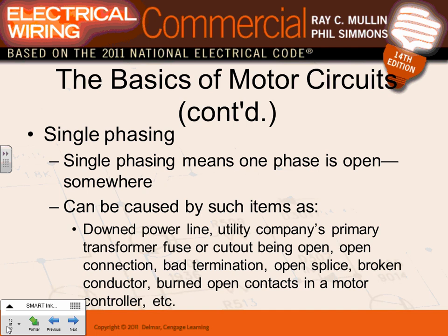That's single phasing. So you have 3-phase coming to your building, and the utility transformer fuse blew, and now you only have 2 phases. Now everything in your building is single phasing. Single phasing is dangerous on 3-phase loads. So single phasing means 1 phase is open, 1 or more.